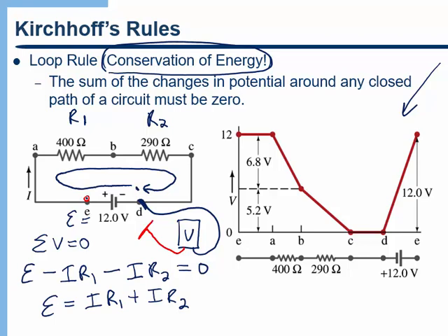So if we connect it at E, then we would measure the voltage of the battery, or 12 volts. So notice here at E, it's showing us the voltage is at 12 volts. If we connect it at point A, we'll notice we haven't lost any voltage along here. We're assuming our wires have basically no resistance. So at A, the difference between D and A is still 12 volts.